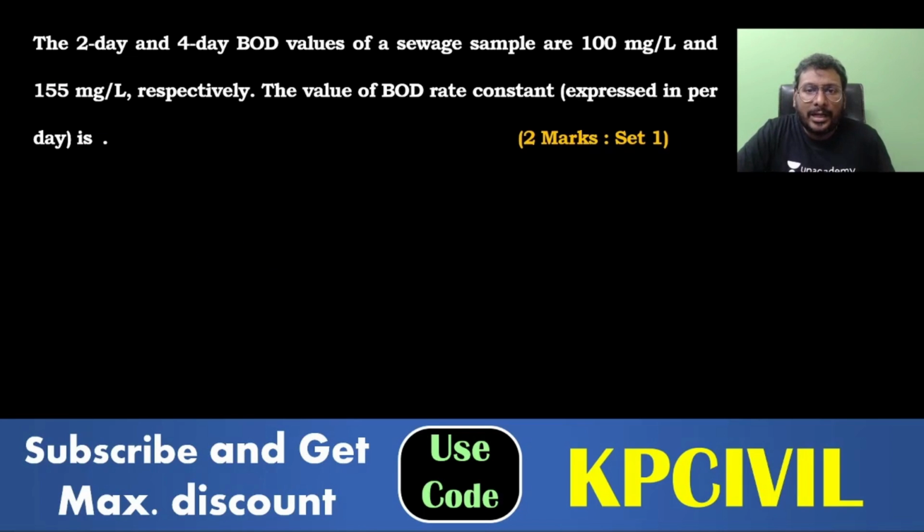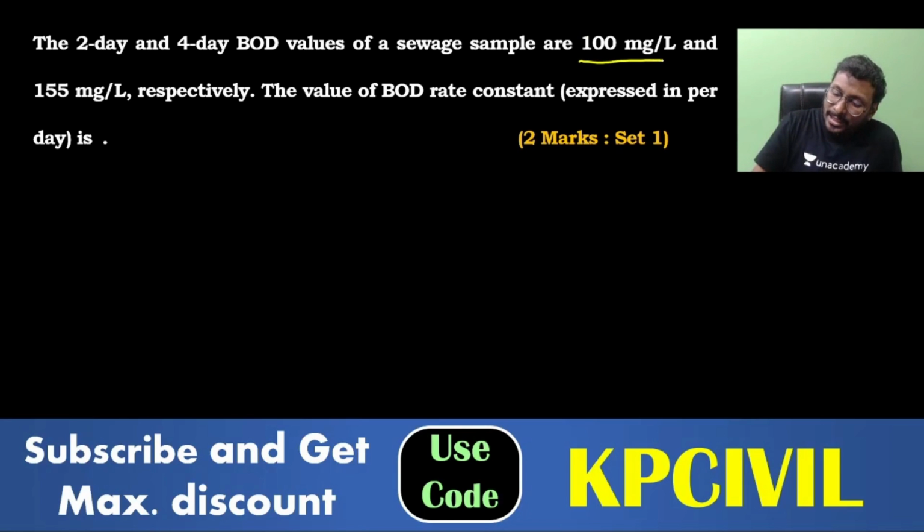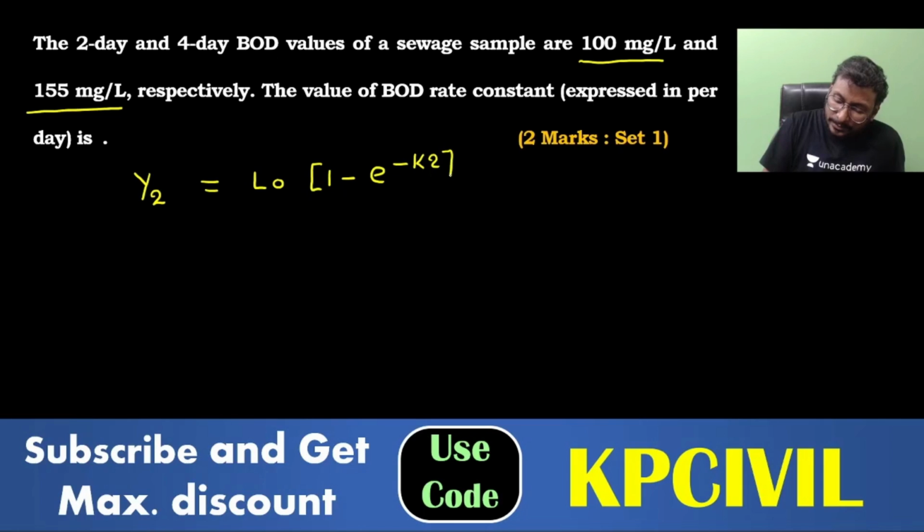The 2-day and 4-day BOD values of a sewage sample are 100 milligram per liter and 155 milligram per liter respectively. Find the value of the BOD rate constant. We'll write down the 2-day BOD, Y2, equals L0 into 1 minus e power minus K2, which is equal to 100.